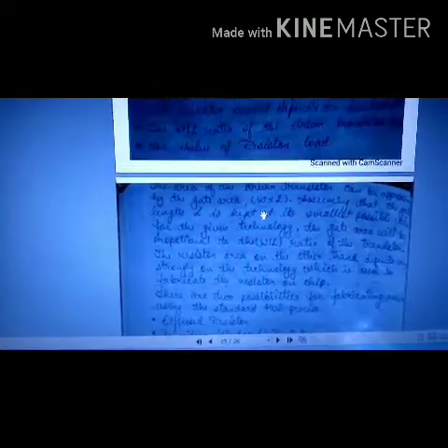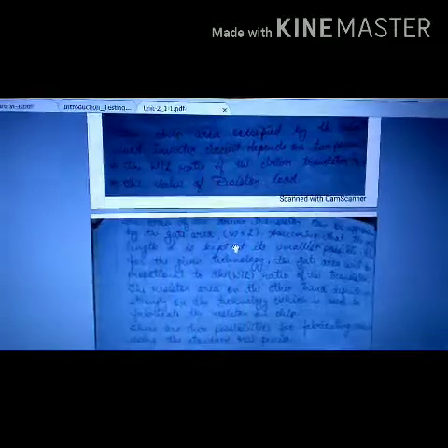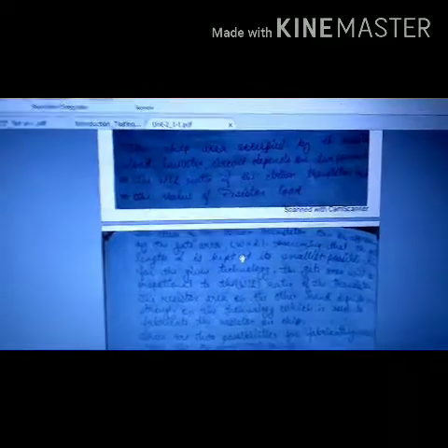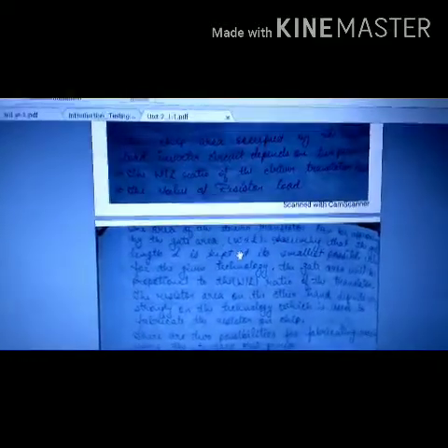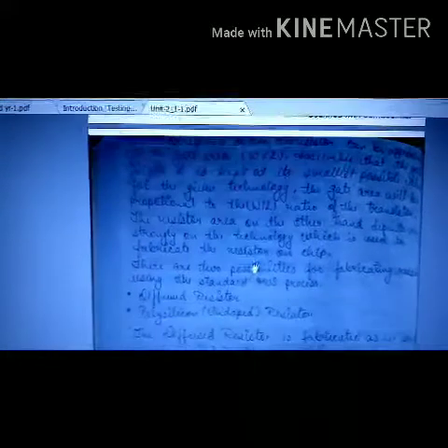The resistor area, on the other hand, depends very strongly on the technology which is being used to fabricate the resistor on chip. W by L can be precisely controlled because of the gate area and whatever device technology we are using. However, the resistance value of the resistor depends greatly on the type of resistor which is being fabricated. Now resistors are basically fabricated by two methodologies.